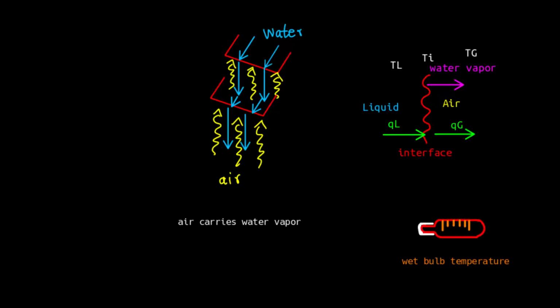Now the hero has a doubt. If I have air and water at the same temperature, then is cooling not possible? Water replies, cooling is possible even if air is saturated or the temperature of water is lower than air. How is that possible? The only thing that matters is the gas enthalpy, which is the actual driving force. We will see this later on.